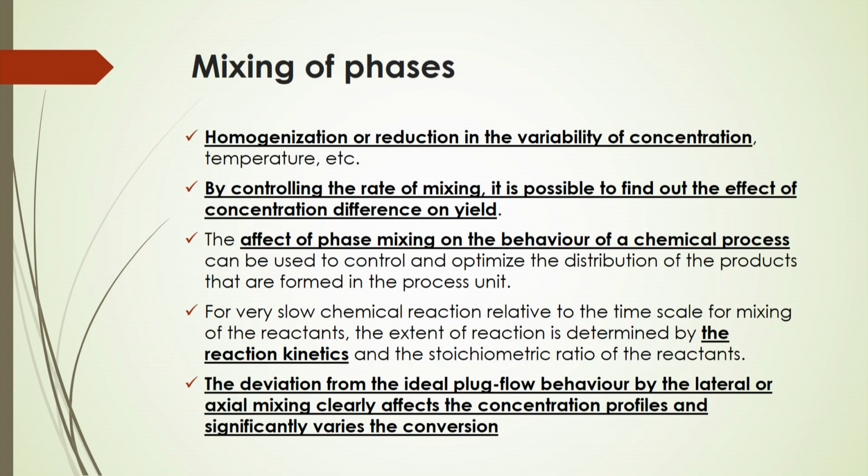Another important aspect of the multi-phase flow system is mixing of the phases, because mixing tells you whether the system is homogeneous or heterogeneous. Homogeneous means the concentration of the gaseous particles will be distributed uniformly throughout the column. Heterogeneous means it may not be distributed equally in all sections of the column.